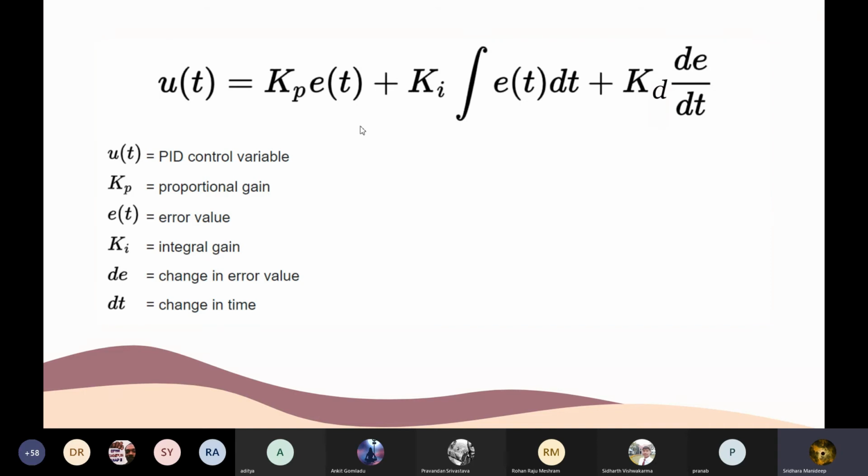We're also trying to implement position control as well. For position control, we are thinking of using two loops. One is just the encoder position, and the second one is also controlling the speed and using velocity profiles so that it moves to that position very smoothly. Yeah, that's all for the control system part. Let's see how to implement it.